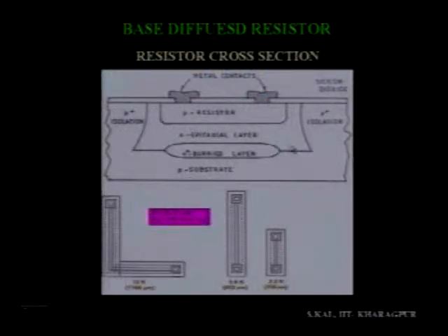How it works, let me first explain that part. So you see here, just like a transistor, as I told you, the resistances are made along with transistors. Same steps will follow for making the resistances. So buried layer, then epitaxy, then P plus isolation here, all is done along with the base, along with the diffusion of the isolation, buried layer, etc., along with the transistors.